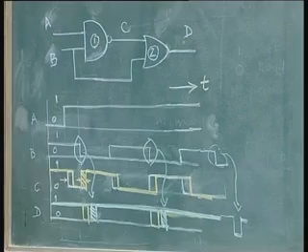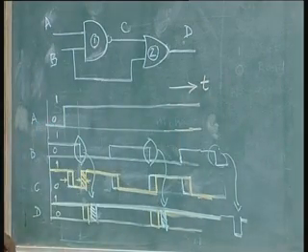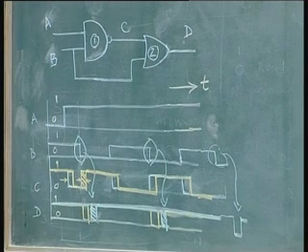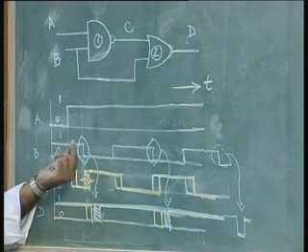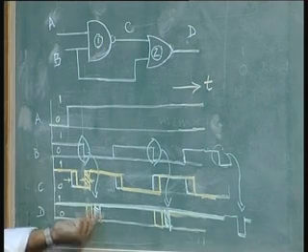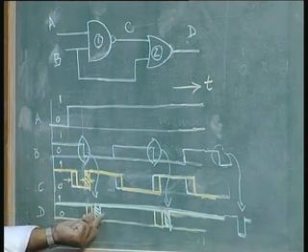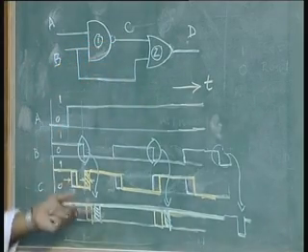So, what I want is, corresponding to the input which is constantly 1, I want the input to be narrow pulses every time the clock changes. Every time the clock changes, in this case from positive to negative, that means negative edge, every negative edge the output becomes a small pulse. So, now I can change this into a positive pulse by, as I said, changing the configuration of the gates.